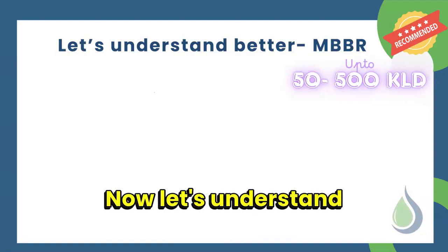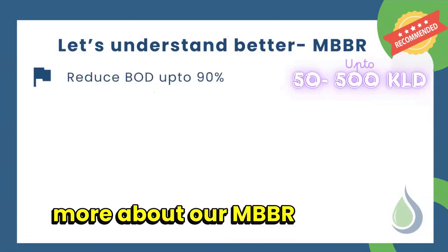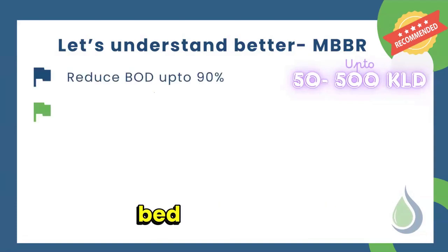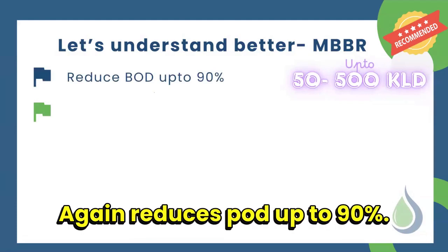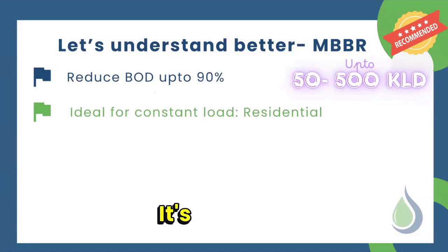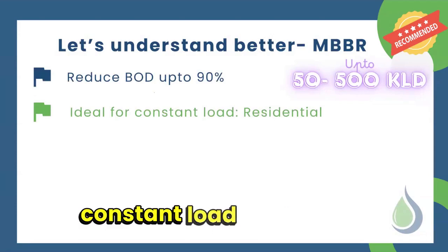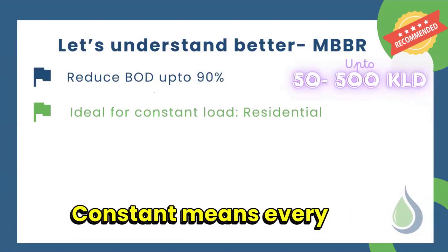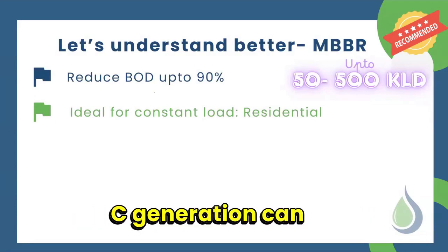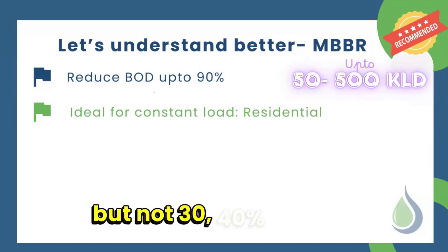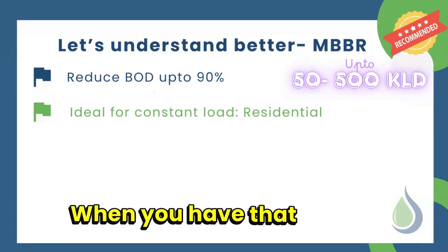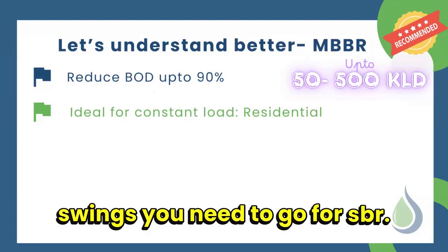Now let's understand a little bit more about our MBBR process. MBBR stands for moving bed bioreactor. Again, it reduces BOD up to 90%, right? It's good for constant load conditions. Constant means every day the sewage generation is constant. Plus or minus 10% is all right, but not 30-40% swings. When you have that kind of swings, you need to go for SBR.